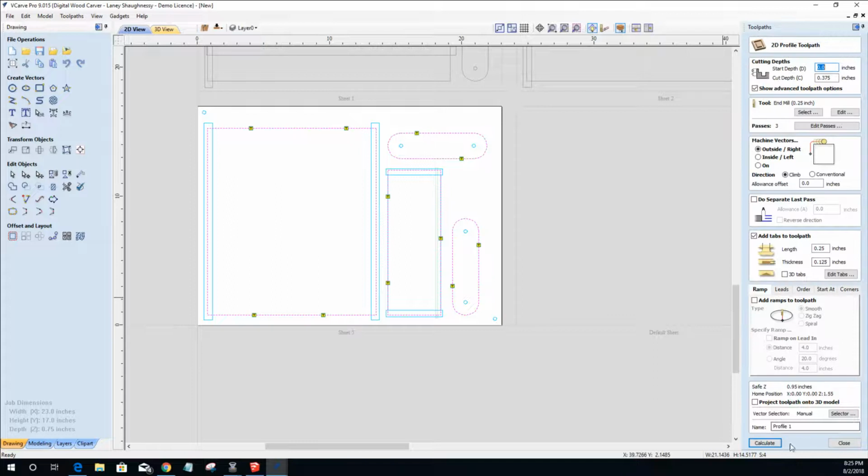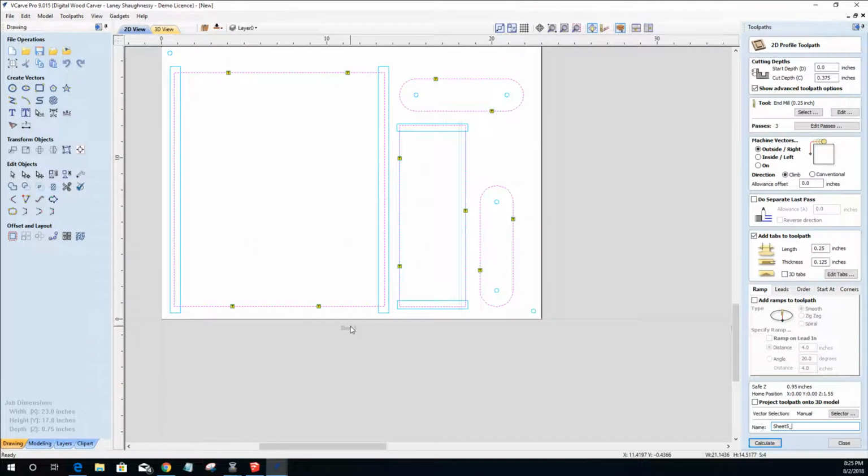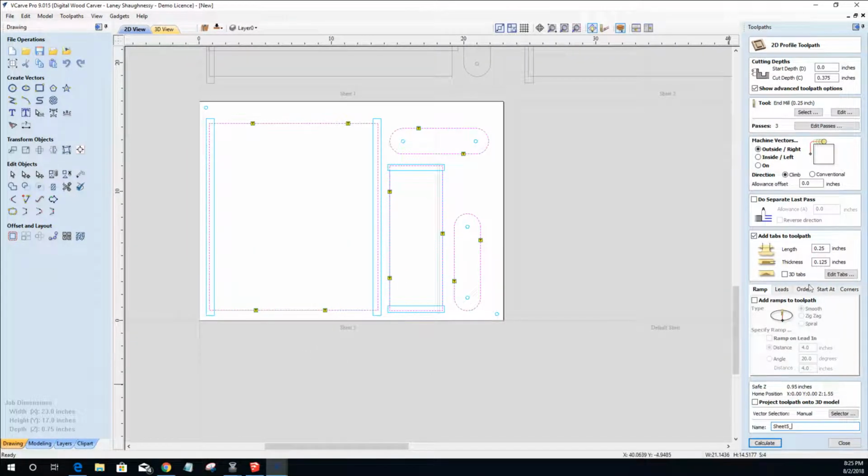And let's go ahead, and this is going to be sheet 5. The only thing that's going to be the hardest part of this project is keeping the names, you know, like what sheet am I on and stuff like that. Sheet 5, and it says it right here underneath in a very faint gray wording. It shows you the sheet name. So sheet 5, side 1. Keep it consistent. This is my profile cut, and it's a 1/4 inch end mill, 0.25 end mill.